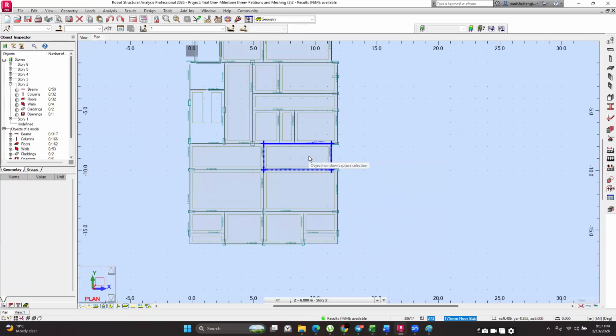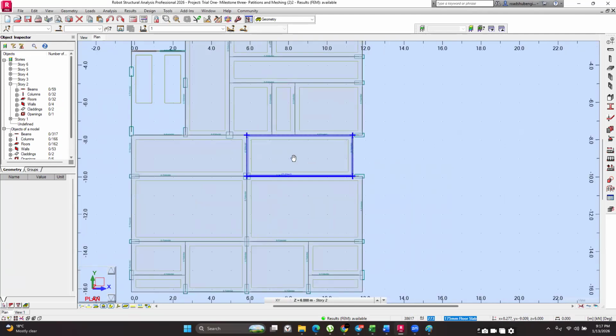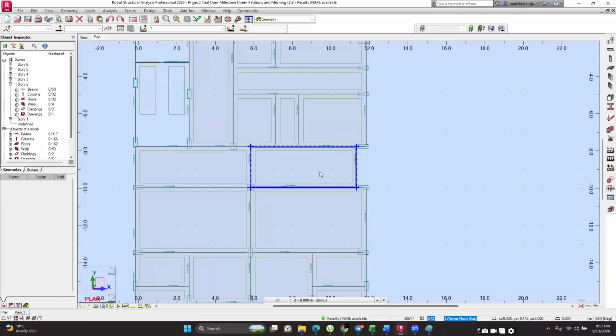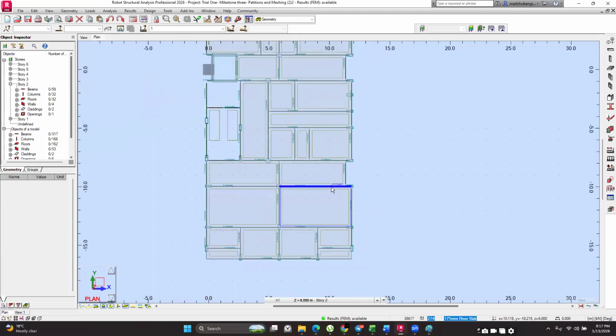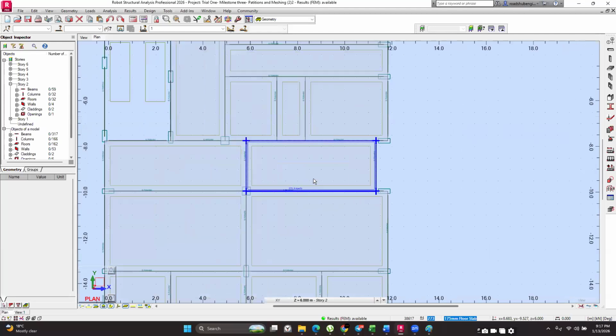That becomes a challenge because you may want to know how the behavior of this panel here is affecting the behavior of this panel here. For example, when you are visualizing the theoretical results for this slab here, we found that we need top bars for this region because we are going to be experiencing some uplifts in this region.